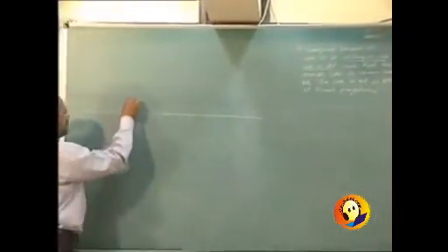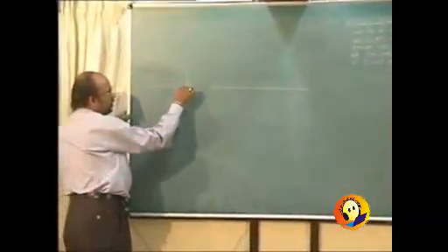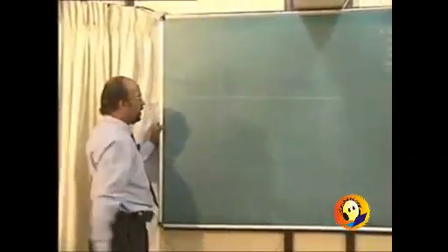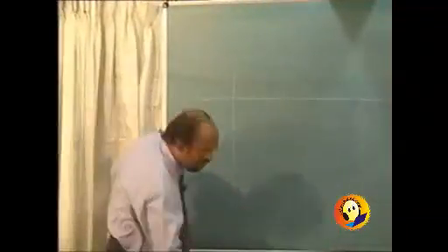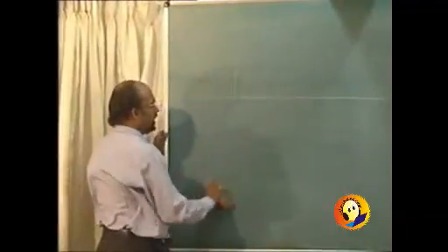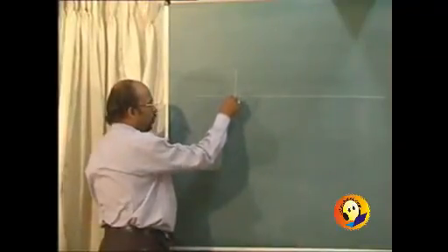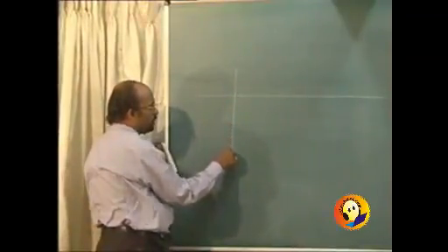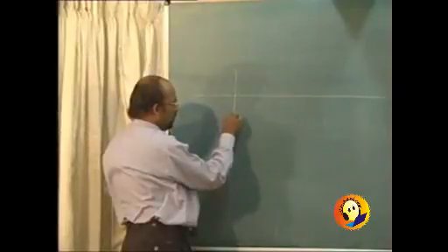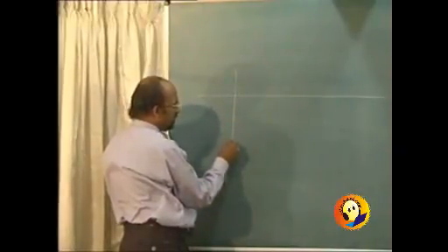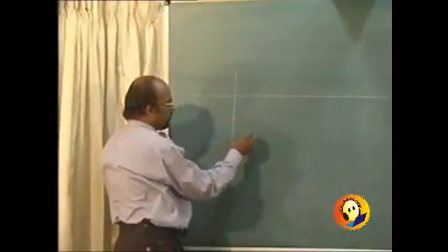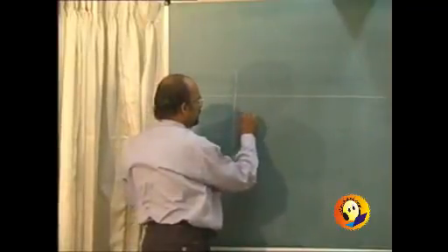And so when we start with XY line, draw a line perpendicular to XY, and then we are required to draw the hexagon with one side perpendicular to XY. The side of the hexagon is given to us as 40. So the hexagon can be constructed.